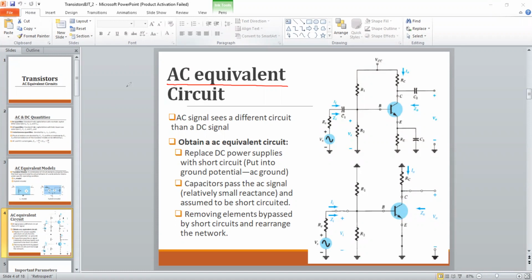This is the transistor configuration we are focusing on. It has a voltage divider bias mechanism to bias the transistor, or place the Q point in a certain well. In addition, we have a collector resistor and an emitter resistor. We have bypass capacitors and coupling capacitors, and the external source is connected to the transistor circuit through the coupling capacitor. The external source has a voltage of Vs and an internal resistance of Rs. This is the transistor circuit configuration we are now looking into.